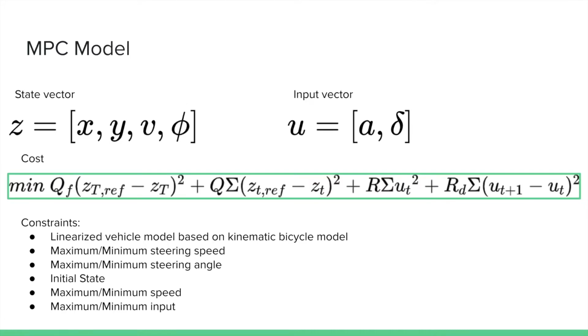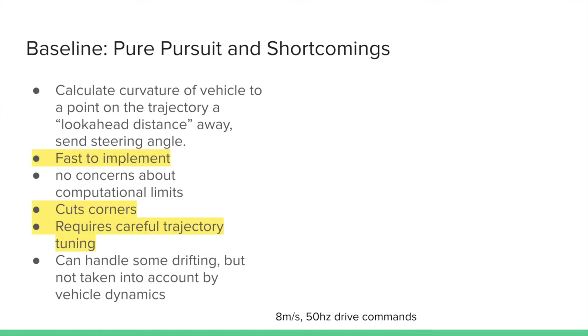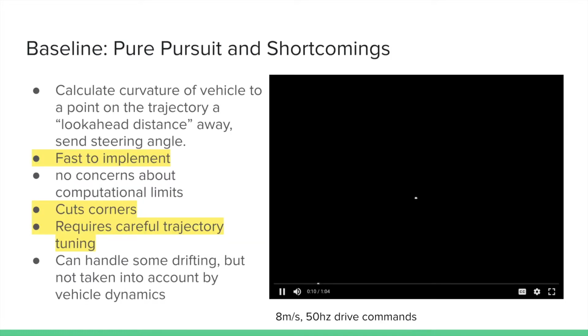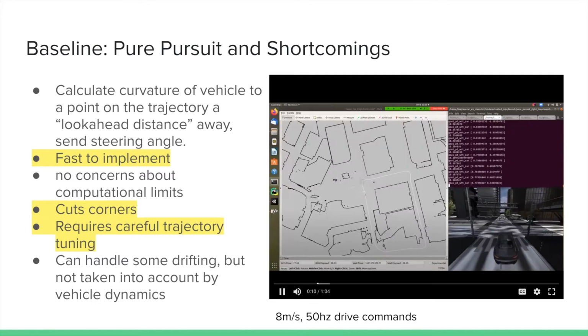the simulator. My MPC problem formulation aimed to minimize the cost over input, the difference in the input between time steps, and also the difference between the car's reference trajectory and the car's predicted trajectory. My baseline for comparison is the pure pursuit algorithm I implemented in MPC.